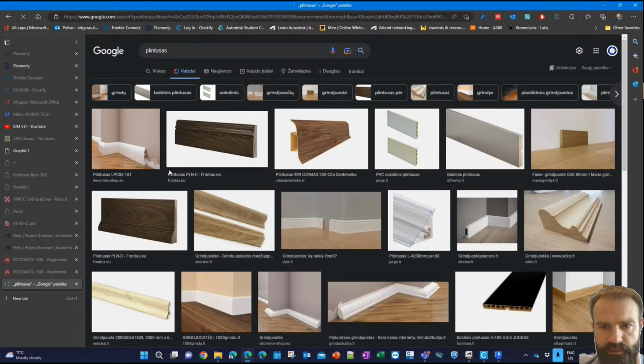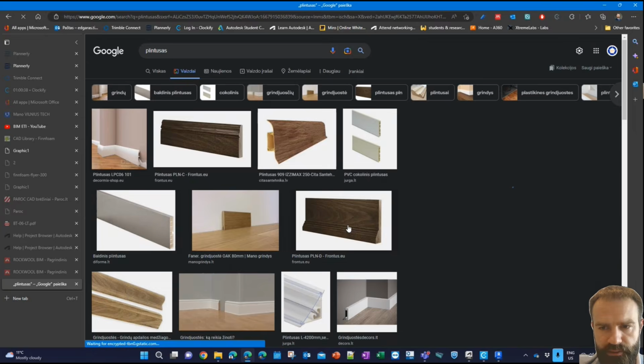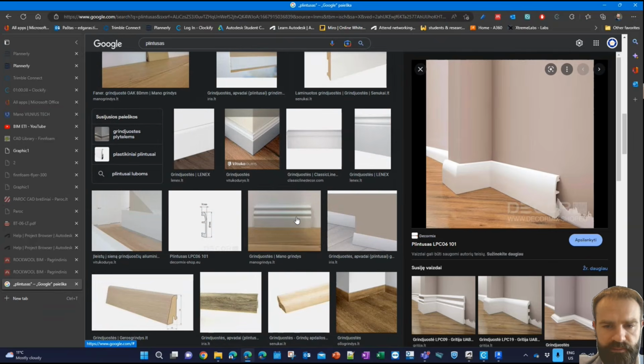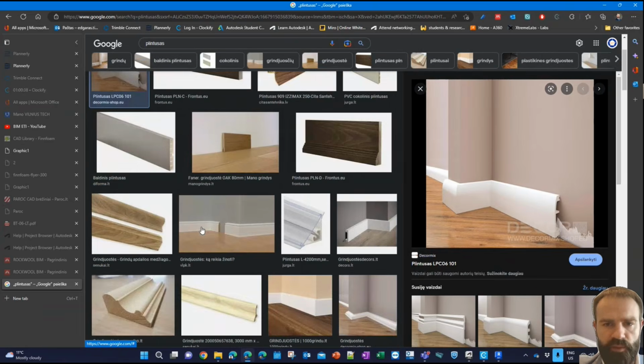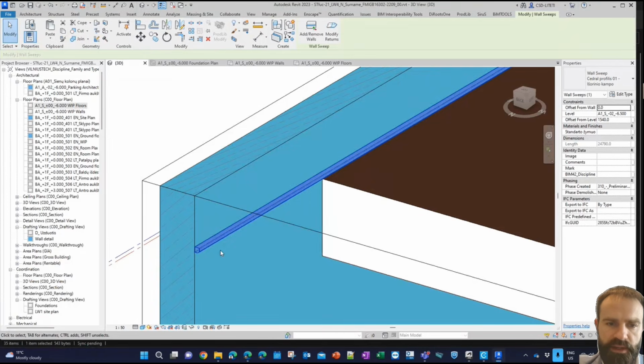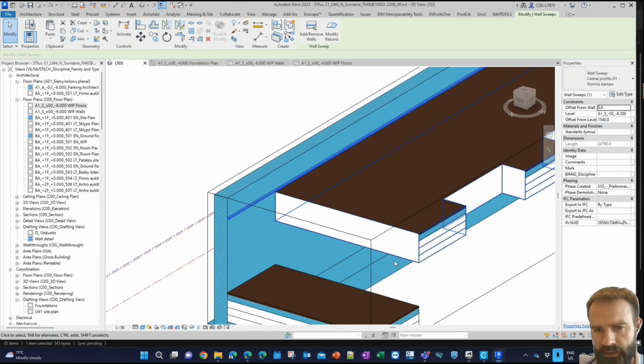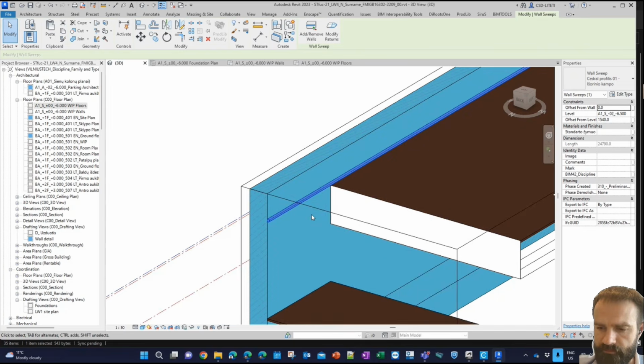So around the floors, we can create this nice element in which we can put some wires and so on, and it hides all these connection parts, my plastering and my floor finish. So all these parts can be done with sweep elements, and these are more related to wall components, not to floors. But yeah, for walls we use sweep, and for floors we use slab edge.